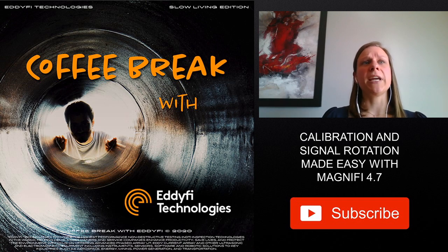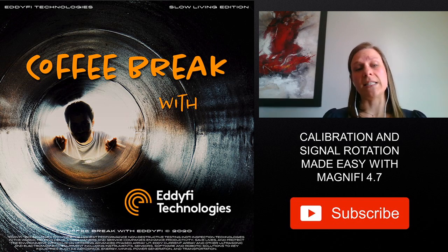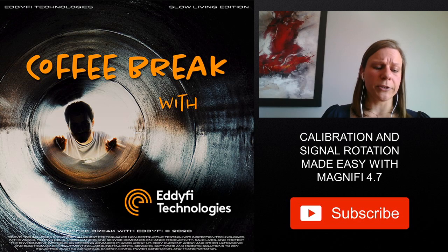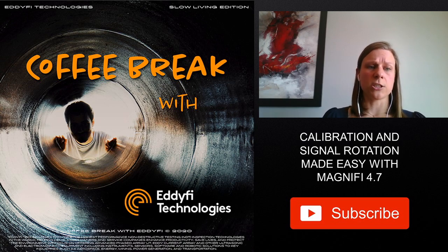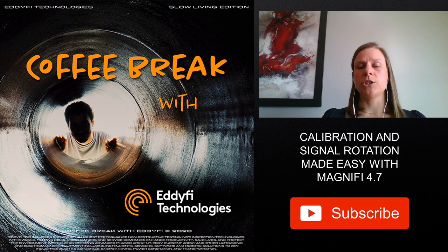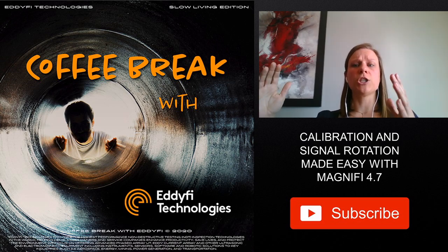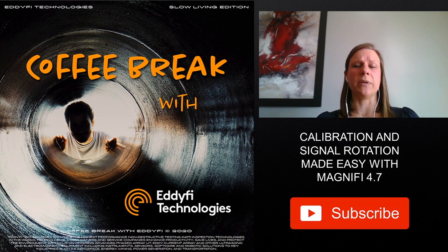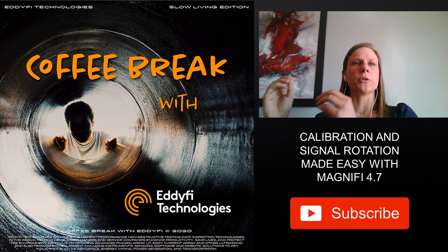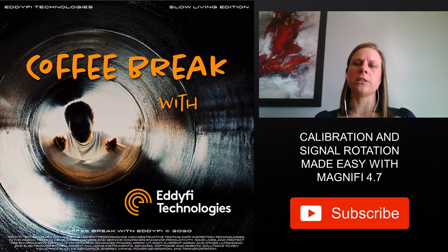So the first feature is what we call the Liftoff Assistant. When we're doing an eddy current inspection, if we want to get good results, we need to adjust the signal at the beginning of an inspection. Whether it is really at the beginning or along the inspection, you might need to adjust the signal rotation a little bit. This will be needed if you're changing frequency. If you remain on the same material but you want to try a different frequency, you will need to rotate the signal.